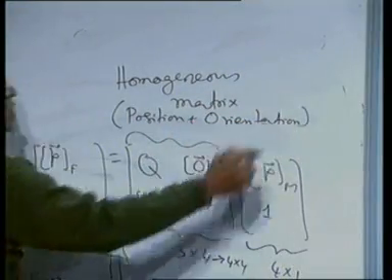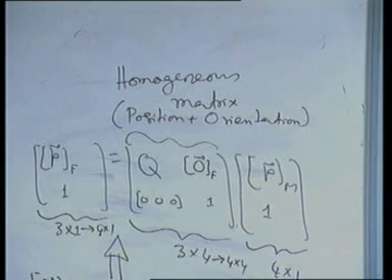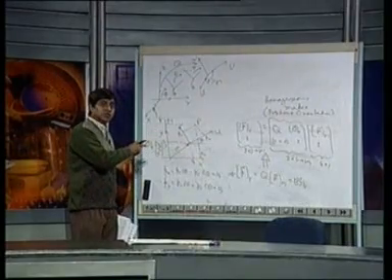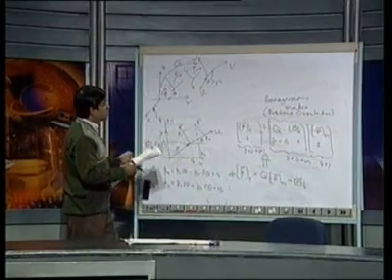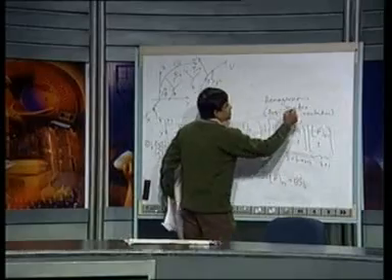In orientation, a 3-dimensional position was converted into another 3-dimensional position, moving frame to fixed frame, by multiplying by a 3 by 3. If you want to convert the positions also, we multiply with a 4 by 4. This is called homogeneous transformation and we represent it with a T.